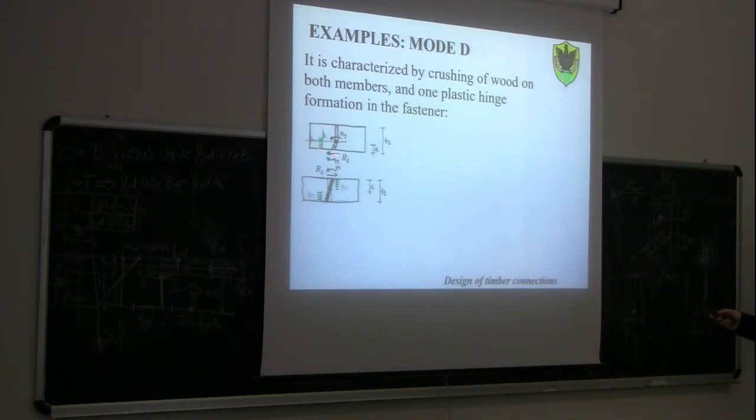It is our unknown. Also the bending moment in the fastener at this section is unknown. And then we will have a plastic hinge formation at a certain distance a from the shear plane. And as you can see here, we will have the inversion of the deformation in a section at a certain distance c from the shear plane.